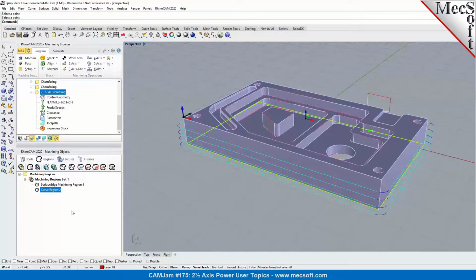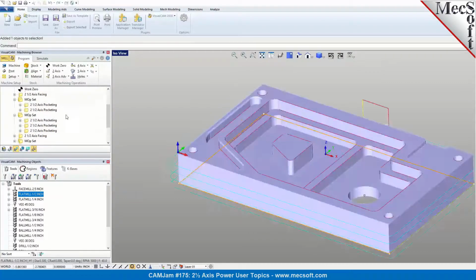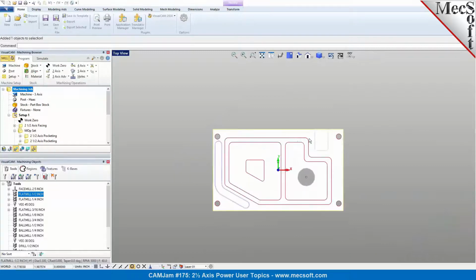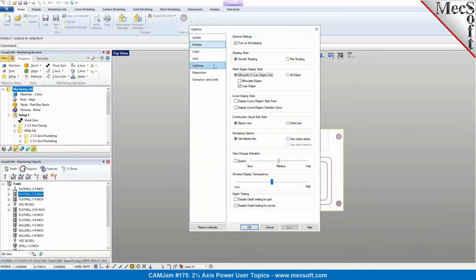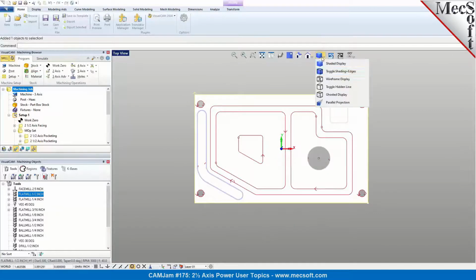The same also goes with Visual CAD CAM for predefined regions and all of our CAM products. Now, for folks who are using our standalone Visual CAD CAM product, I'm going to quickly show you how we can change the start point of the underlying curve using our host CAD system in Visual CAD. So if you're selecting the curve as your part region, you can also display the curve direction and arrow by going to the options in Visual CAD. You can display it. So that displays the curve direction, start point, arrow. And you will notice that I'm going to switch the view to wireframes.